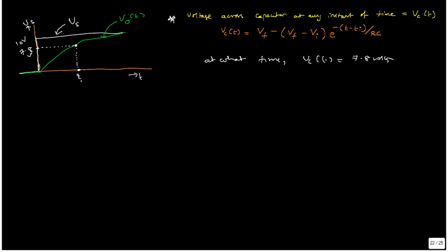If you know the voltage across the capacitor, you can calculate how much time it takes to reach that value. And if you know how much time you are giving as input, you can calculate how much voltage a capacitor can charge. These are the two things you can calculate from this equation. So again you are going to use this equation to calculate the time.